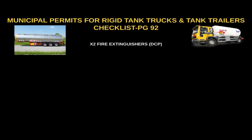So just a reminder, remember with tankers, we never remove the placards. Because even when we offload, let's say we offload the petrol or diesel, whichever product we're transporting in here, we never remove the hazard warning sign as well as the placards. These ones stay on for tankers. Please always remember that. We do not turn these ones around. Why? Because at the bottom of this tanker, there may still be residue, maybe leftover product, which means this can be highly combustible. It is more dangerous when it is almost empty.